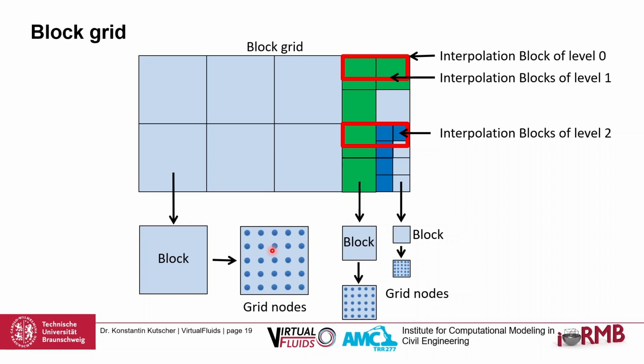For me this was very surprising because I only know VirtualFluids, and for me it was okay. I spent maybe 20 seconds to generate this coarse block grid and another 20 seconds to generate the nodes, and I can see something now. I can start the simulation, see the first 1,000 time steps, and decide if this is right or wrong.